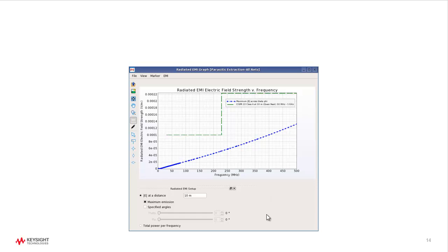So you can actually do a kind of virtual EMI chamber and get pre-compliance of EMI after making every change, to make sure you don't violate things by introducing an accidental unwanted side effect for your modification where you then violate the FCC mask, which is what you don't want. So this is very powerful.